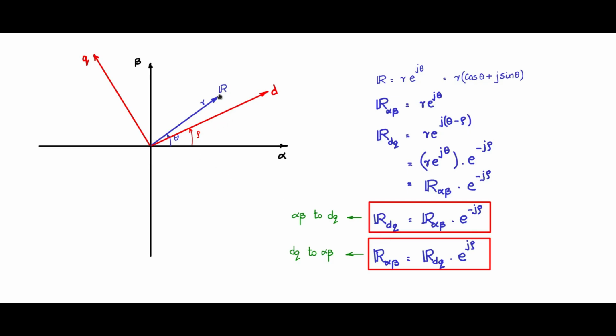What we are going to do is, this vector we saw was a vector which was rotating in a circle, and then we will make dq also synchronize with r and keep rotating. So the vector is rotating in a circle, going at speed omega t, so the angle theta is going at omega t. We will make rho also go at omega t, so it looks as though d is following this vector r synchronously. Then the angle between r and d will be the same at every instant of time, though both are rotating.